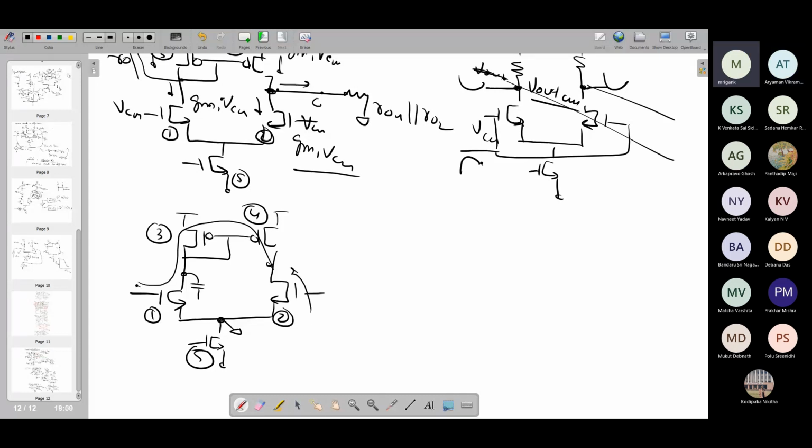In the first path, we have the first pole here, which is again a low impedance node. Therefore, it is not going to matter. And second, at this node, which is the high impedance node, which is going to matter. For the second path, that is the only pole. So the first path gives you gain like (1 plus s upon p1) into a2 upon (1 plus s upon p2), where p2 is just the dominant pole.